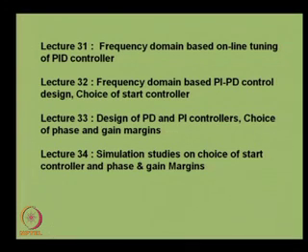Lecture 31, 32 will discuss about the online tuning of controllers using frequency domain. In the frequency domain based controller tuning, phase and gain margins will be the two important parameters that are to be taken into account, and we shall try to design robust controller based on frequency domain.